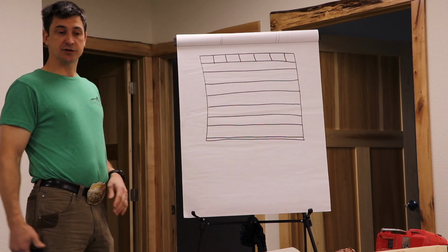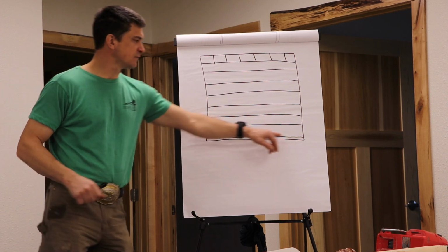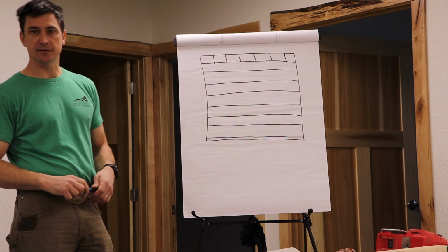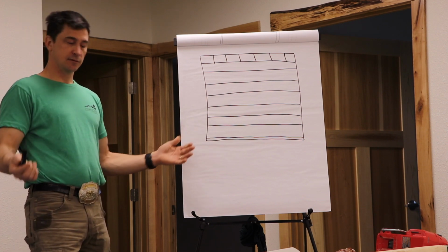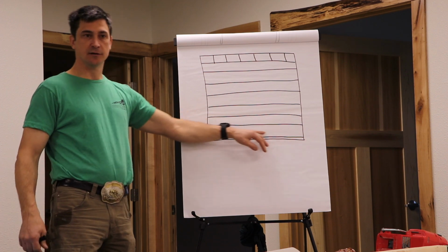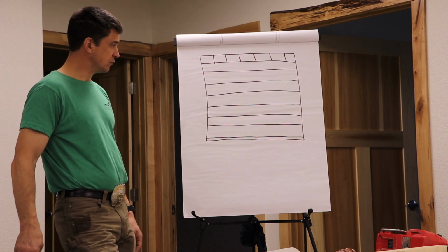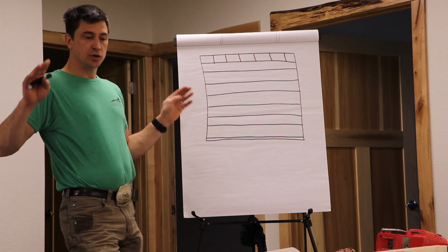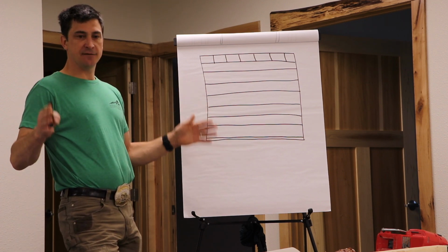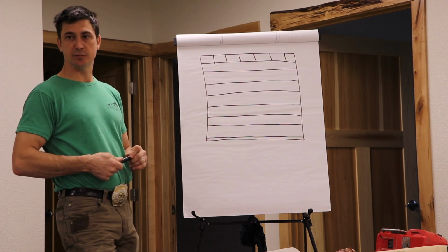The somewhat conscientious guy will be like, I'm gonna solve that. I'll just stuff some fiberglass in there when we're framing that thing. Then, it takes weeks to frame the house and it gets full of water in there and other messes and that. So, you do not have to have a floor joist on layout if it's going to be a problem.